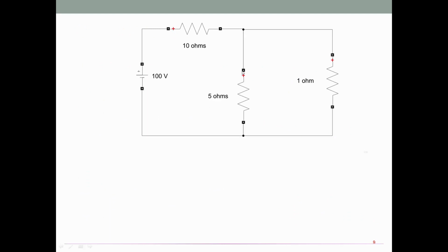Let us take down the same circuit. Now I'll tell you how to choose loop current, which already been discussed. You can choose your own direction. I am choosing clockwise. Similarly, second loop I am choosing clockwise. As I mentioned earlier, no need to choose branch current here for this category.